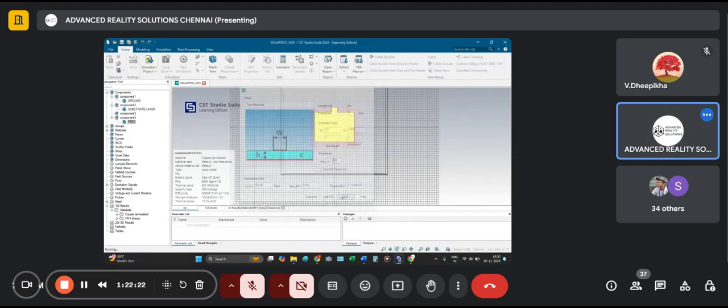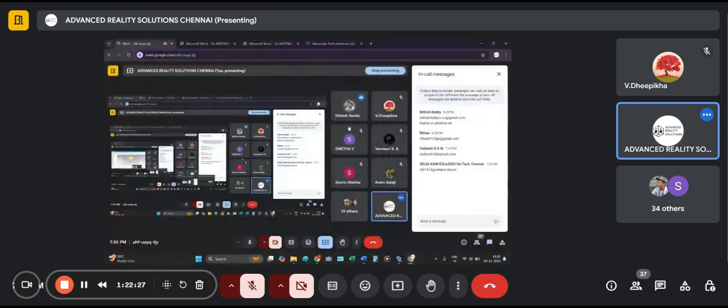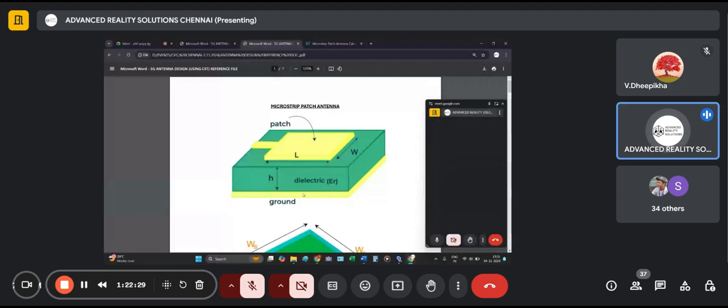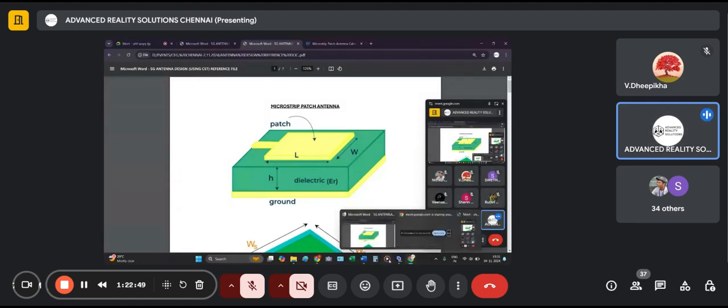Okay. So it is a standard value like what we used in design of ground layer. We have taken 0.035 for copper clad. Copper clad is the base element in PCB design, which is the first and foremost layer on which everything else is fabricated. So it has a common value. Or you can define it like, sir, I want to design my antenna with a ground thickness of 0.045. Yes, go ahead, no problem. But the standard value is 0.035.